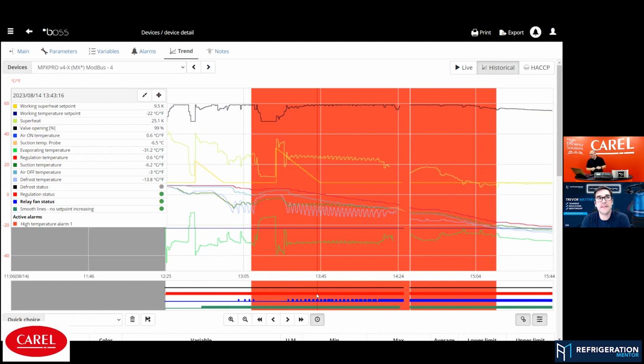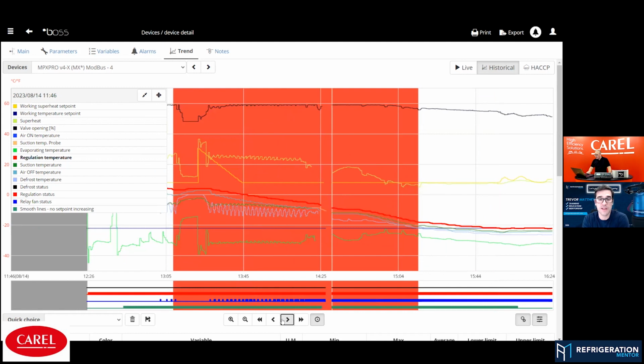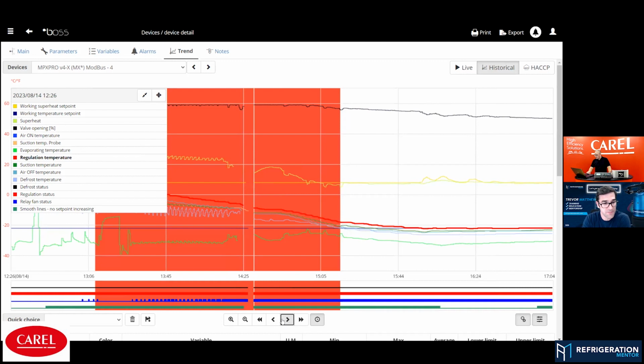So you've got to think about low temp applications. When you open up the door, you're going to want to stop the fans. And that's what it was connected to, that door switch, just like you said, because you could run into lots of issues just like this. Exactly. It's strange though, how it was open and then closed and open and closed. They must have been trying to shut the door. That's what it kind of looks like, right? The relay was opening and closing, open and closing. They couldn't fix it. Then all of a sudden it's just open, it looks like.